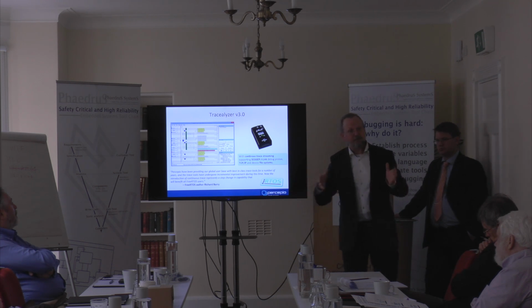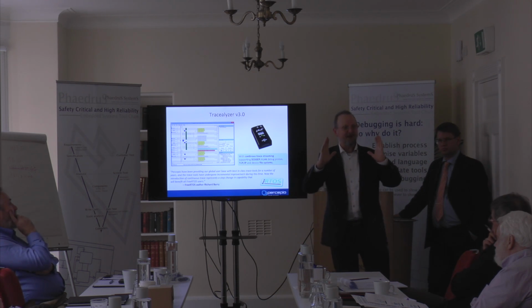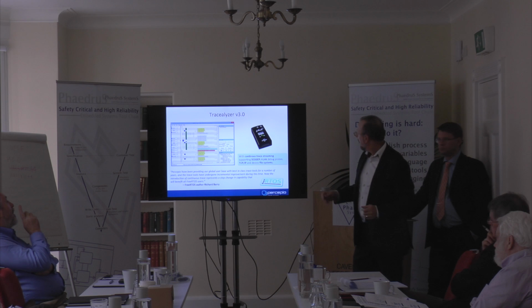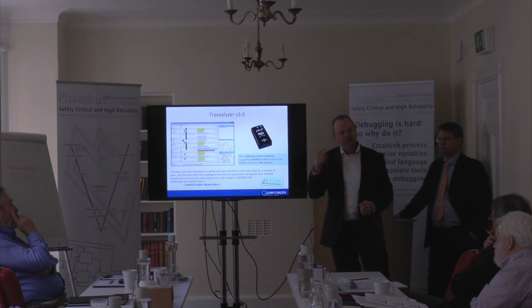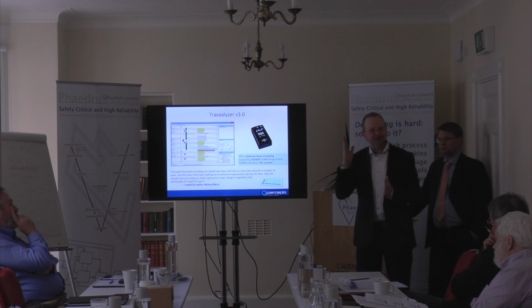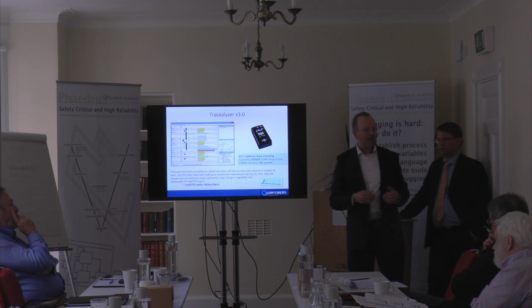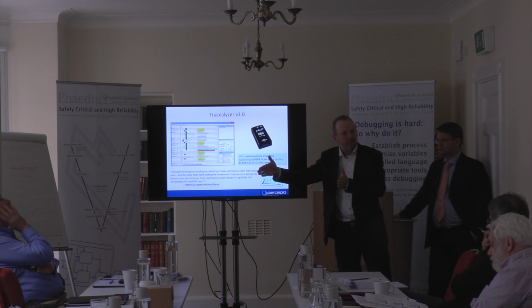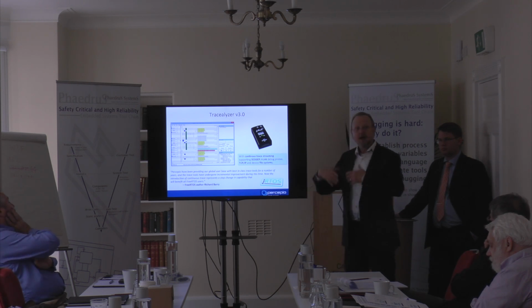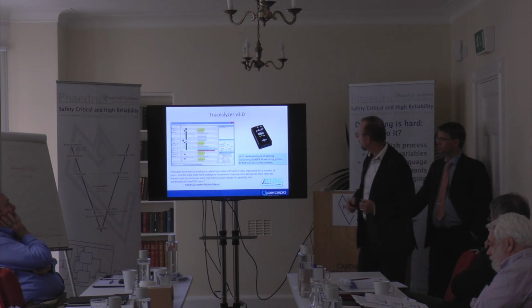So you get a couple of seconds as a snapshot of your elephant, if you will. The other way is to run it as a ring buffer and continually fill it and wait for it to stop. So you convert it into a software black box. You get the last few seconds of whatever you're running, and then you can look at it in all kinds of detail.